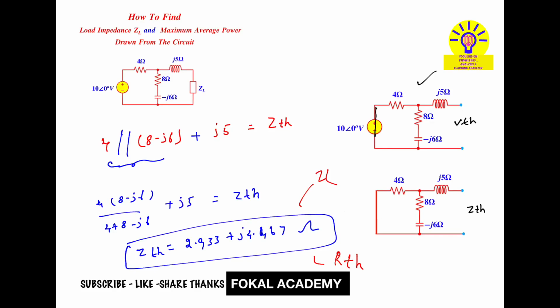Observe carefully here. The load given is an impedance. Whenever the load is an impedance, what is the relation between the load impedance and ZTH? ZL is equal to the conjugate of ZTH. Suppose in place of the load, a pure resistance RL is there. Then it becomes the magnitude of ZTH. But here the load is complex, that is, an impedance, so use this formula. ZL is equal to the conjugate, meaning apply the minus sign to the imaginary part.